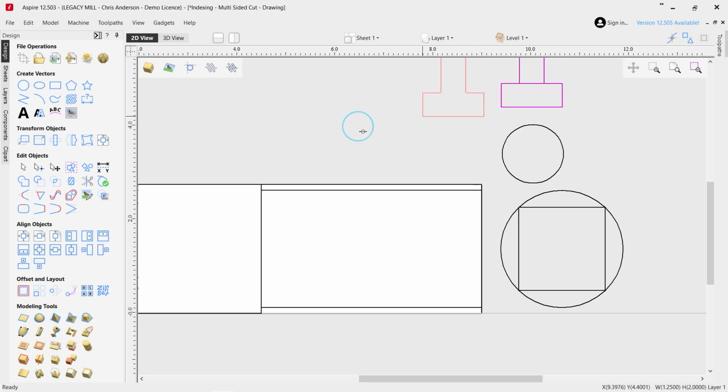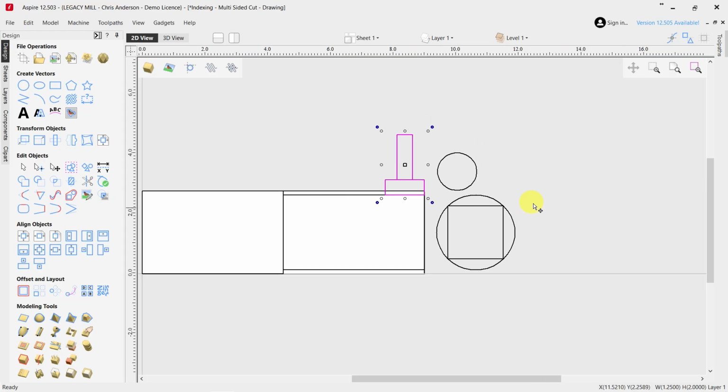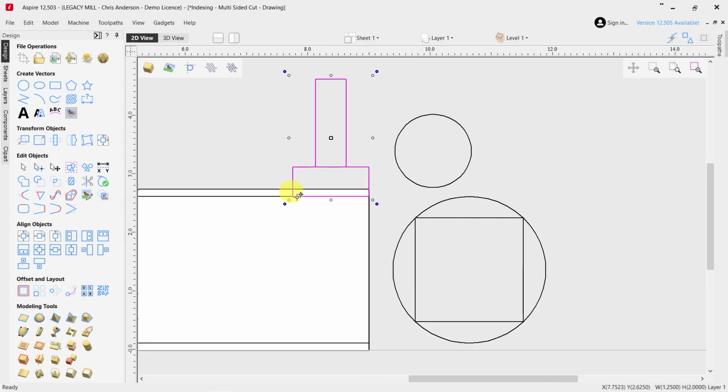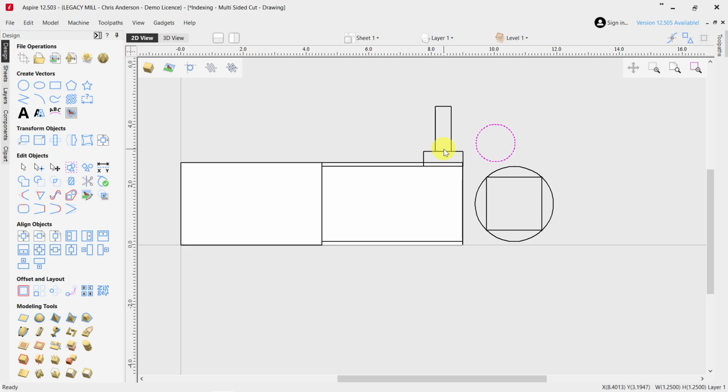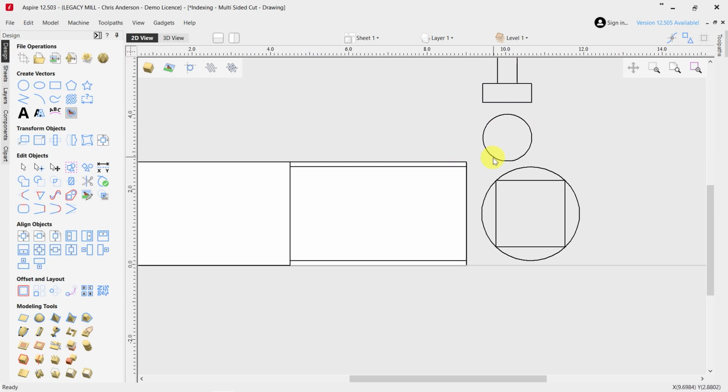Now, this is going to approach the material in the same way as the multi-sided surface. It's going to be taking a surfacing cutter, typical for this type of application. It's going to have a starting position. It's going to be traveling down the stock until it gets to the ending position. And then it's going to cross over the width of the part and then zigzag its way back across the material. Technically, if we look from a top view, it's a little easier to understand versus from a side view. So this is a side view, is what that cutter represented. This would represent a top view.